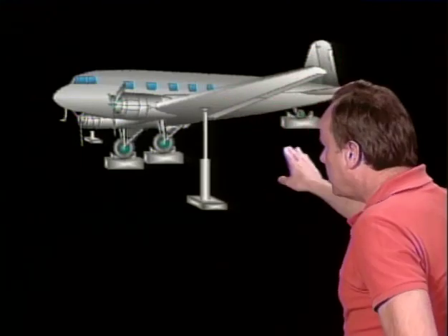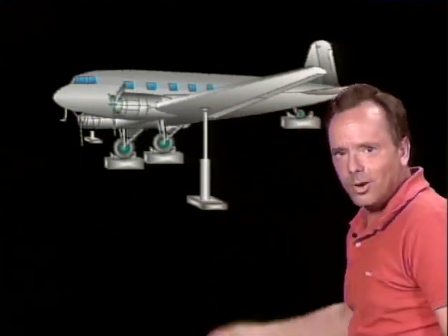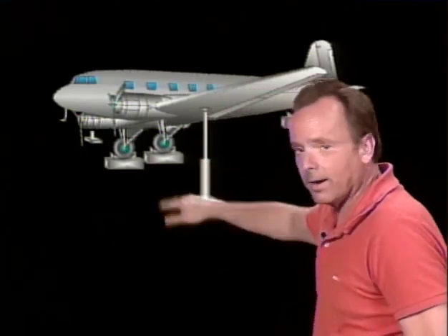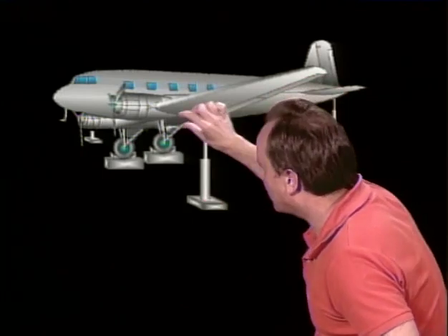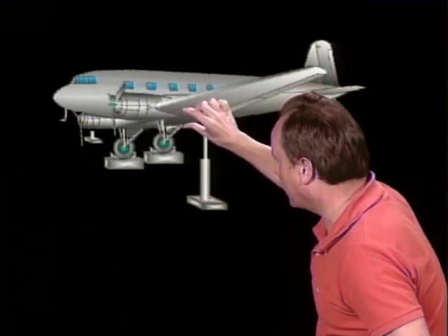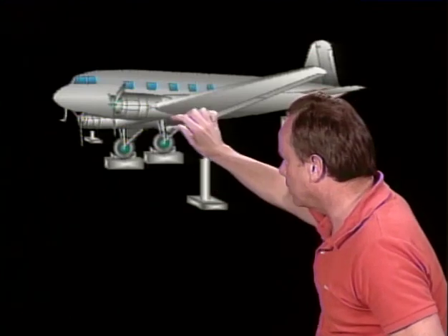Now let's assume you want to jack up an airplane to weigh the aircraft for weight and balance purposes, and you're going to do it with a magnificent DC-3. The question is, should you do it indoors or outdoors? They want you to generally jack up aircraft for weighing indoors. They don't want the wind to affect the weighing of the aircraft. And also they want you to know, before you jack an aircraft, you need to reinstall any critical stress panels or plates, because if you have load-bearing stress panels off the aircraft and you jack it up, you could put a stress on other parts of the aircraft that it's not designed for.